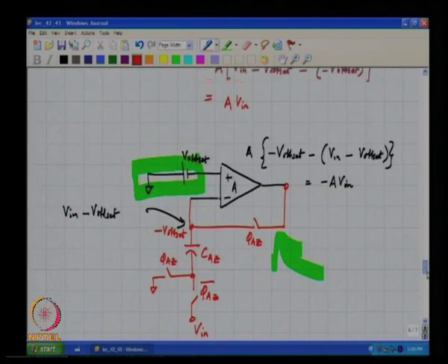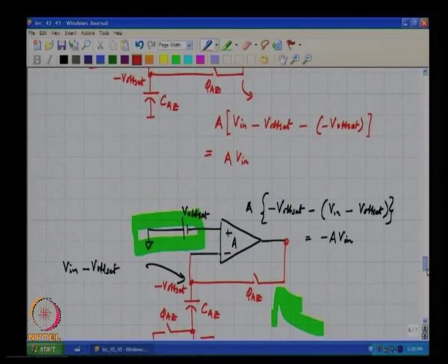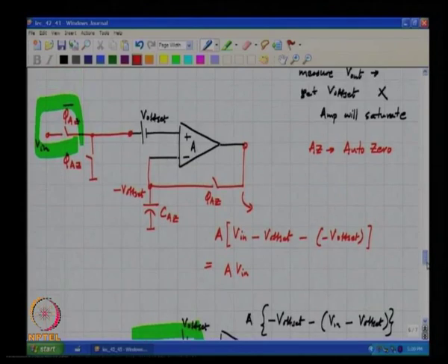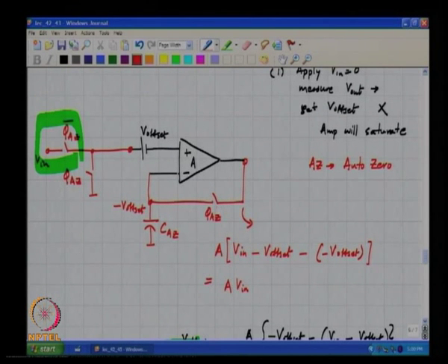all right. Of course, one thing that none of you caught is that the output voltage will not be exactly equal to V offset. I mean, during the auto 0 phase, for instance, here this switch is shorted and this is grounded, this output is going to be minus V offset only if A is infinity. In practice, it is not quite infinity.